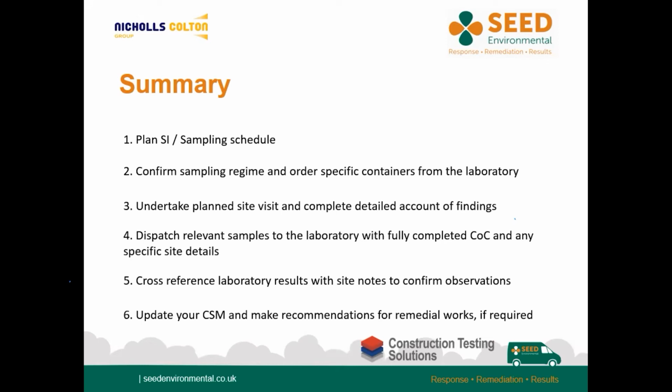When the laboratory results have been received, compare the results to your field site notes to ensure that all lines of evidence marry up. If you consider there to be a discrepancy, can you explain it based on your field notes? If not, the laboratory should be able to provide assistance, as Amy has outlined earlier, with re-extractions or further information on their analytical process, which may help to explain the results.